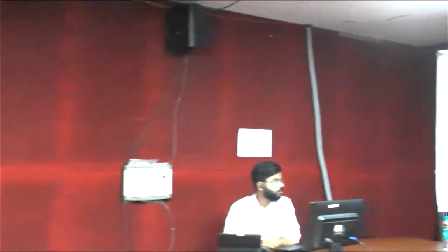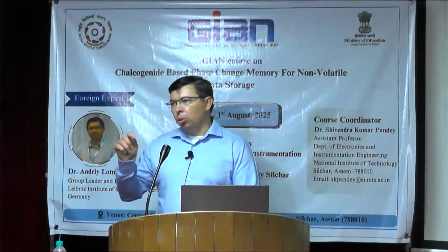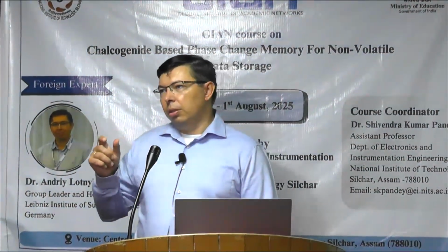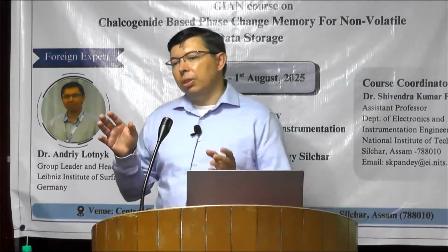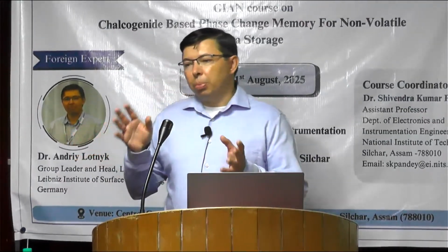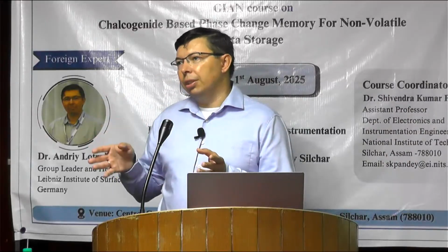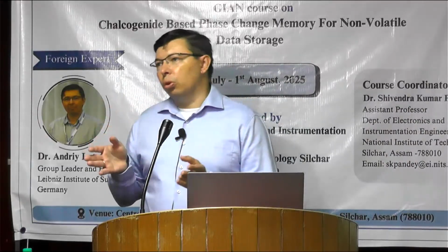Yes, you can compare, but in phase change memory technology, you apply a pulse. It's not a constant pulse. You need to apply a pulsed electrical pulse. And of course, you will have some spread in the values of resistance from one device to another, depending on the materials, because it can be non-uniform.